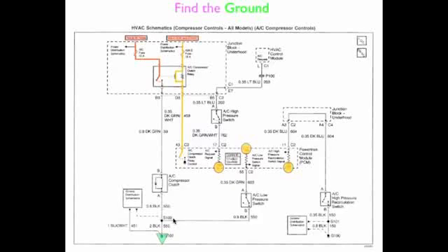We have the first ground. We have our second ground. And then there's also a ground inside the PCM, but this will be a switched ground. Now, how does this ground travel? Well, this one just travels up, goes through the coil because there's continuity, and it stops at an open. Now, the second one is the same ground, but it is spliced. It comes over, and it goes through this low-pressure switch, which was in the closed position. So this ground is going to travel through that switch and go to the PCM.